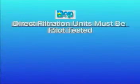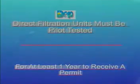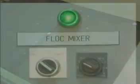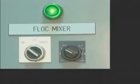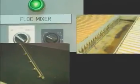Direct filters can be utilized in applications where the source water turbidity is normally low. Direct filters are required to be tested or piloted at the source for at least 1 year before they will be issued a permit. Different types of direct units utilize a combination of flocculation or flash mixing, contact clarification, and multimedia filtration. One group of direct filters uses an upflow clarifier followed by multimedia filtration.